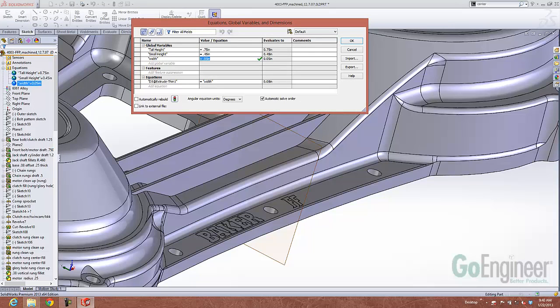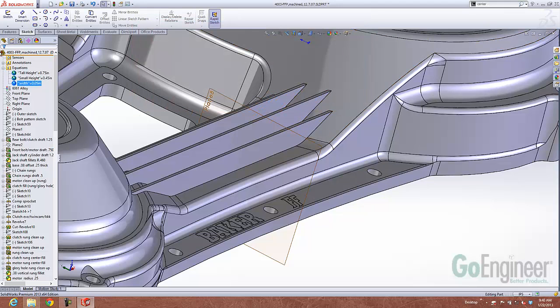What this allows is for a more consistent user interface, so we know, okay, this is going to be 0.5 inches versus 0.505 millimeters. Also, when I'm making changes, so if I were to come down here and say millimeters, global variables in the past, they didn't have a unit of value. So if I said they were 1 inch and then switched the units to millimeters, they would be 1 millimeter. By having those values in there, it's a lot easier to understand when I'm reading the dialog box, as well as if I'm switching units. We have a more consistent rebuild.